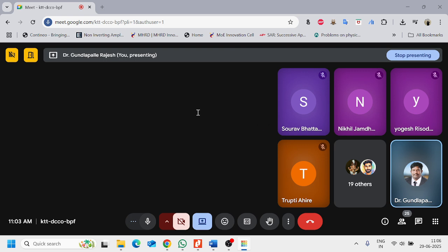So once you make this low, it has to be off. Low means pressing: when the button is pressed low, we are giving the excitation. If you are releasing it, it is said to be high. So let us take this and put it here and make it high. So whenever it is released, your LED has to be off. Off in the sense it should go low.